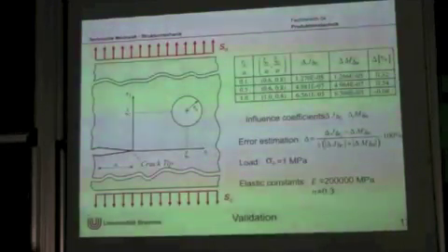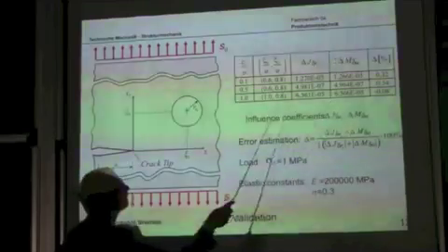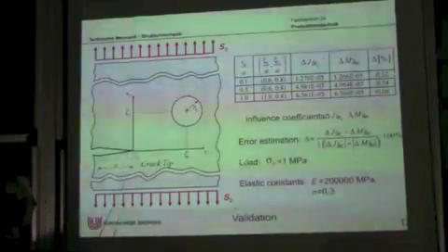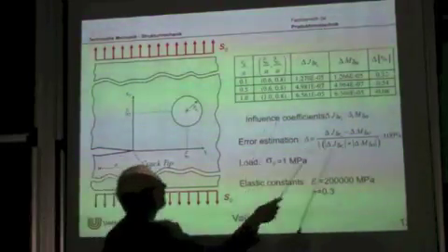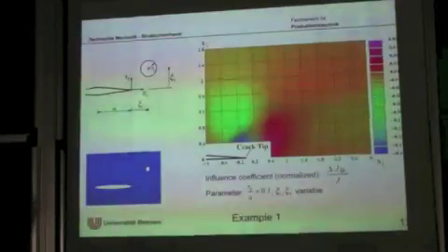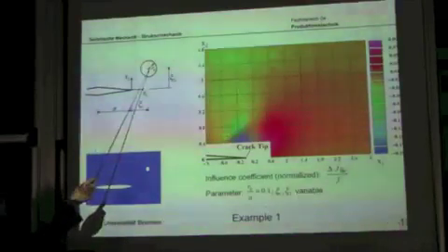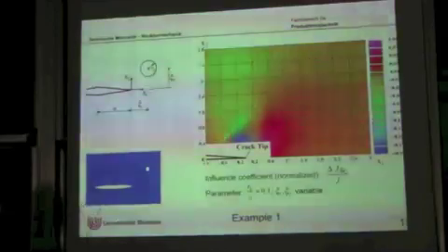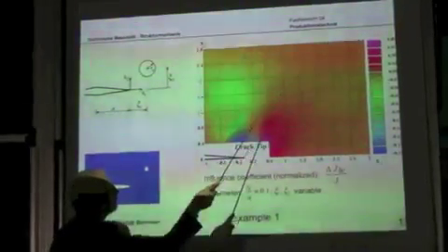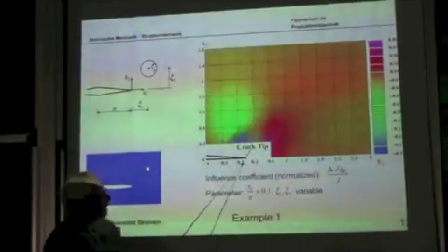And we made a post-processor for this problem. And here we just checked if the influence coefficients are the same, if you increase the hole or you extend the crack. And we just checked that it's working, and then we did some examples. For example, using reciprocity, we calculated an influence surface. Therefore, if the hole at any point here is increased, you can immediately see from the value at these grid points how the crack is changing.